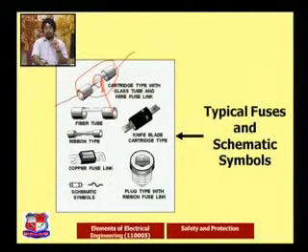This wire is not going to melt at an excess condition or abnormal condition, and that is going to create a problem, because in that time this circuit is going to still continue, and it may happen that due to the excess current, the equipment is going to burn out, not the fuse. Actually, that's why the fuse is the weakest part, because the fuse is going to break down or that wire is going to melt, and in that way it is going to give protection to the circuitry.